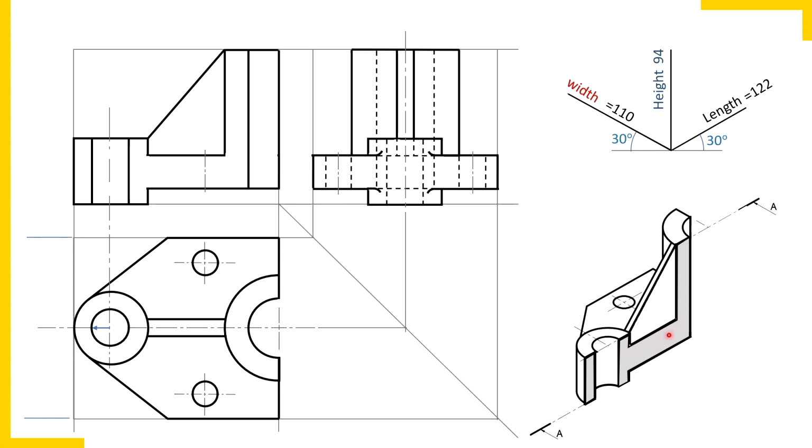So whether we should erase these boundaries? So no, as I told you, ribs, that is those plates with largest surface in sectional view, are to be assumed uncut. So we should assume that this plate is not cut. That means we must not draw hatching lines here. So one more rule on sectional views. If largest surface of a plate appears in sectional view, then don't draw hatching lines on that surface. So here on this trapezoidal surface, we are not going to draw hatching lines.